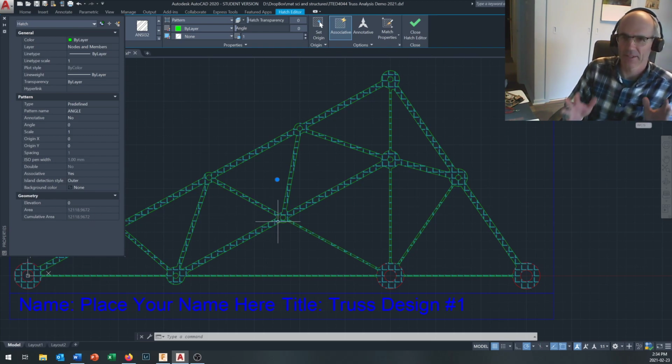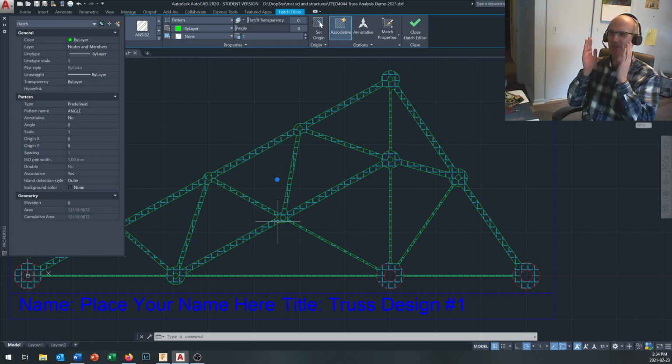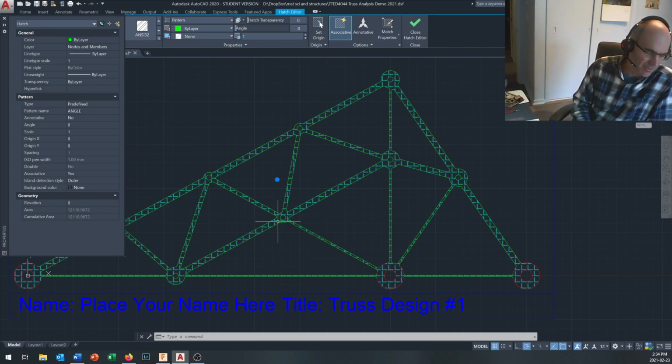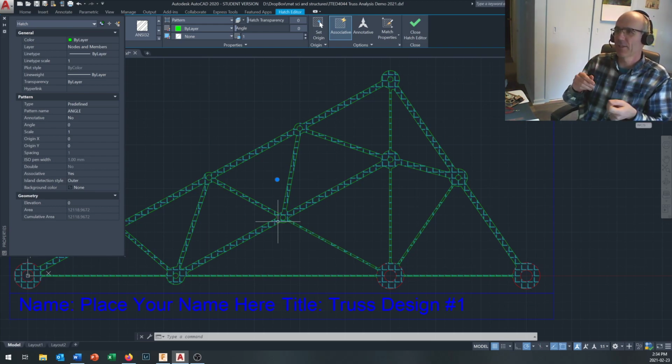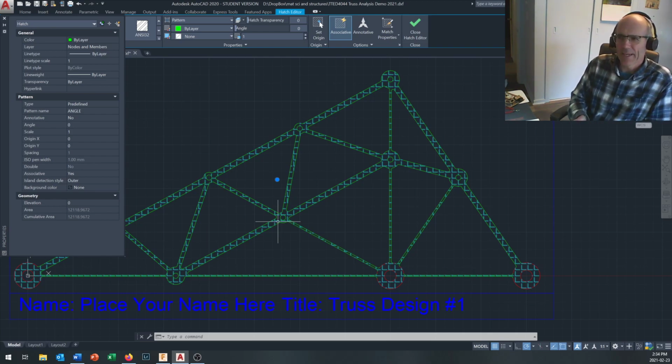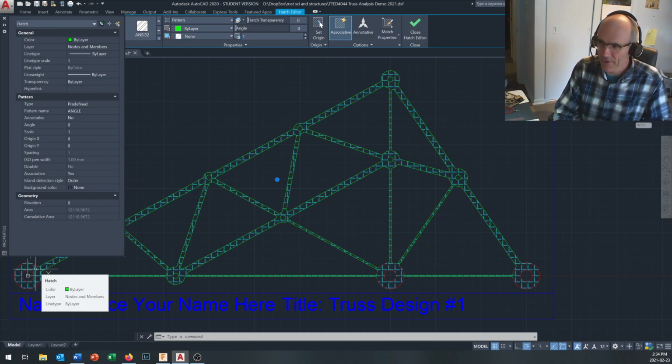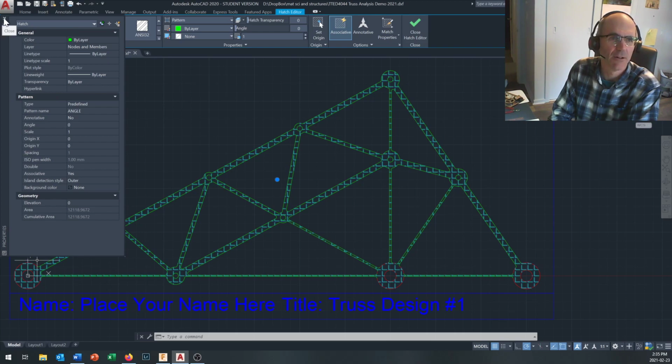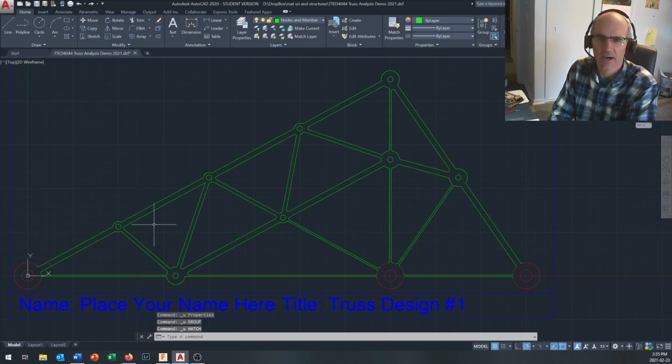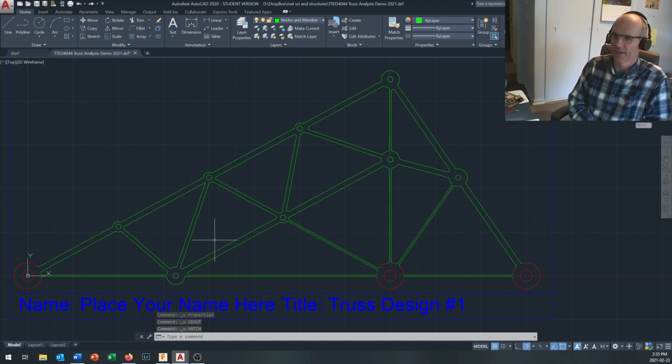this tells me that my truss right here, this piece of MDF, is going to weigh 32.7 grams, which doesn't sound too bad because when I go make it a two-sided truss, that's going to take me up to 64 or 65 grams, and that might leave a bit of mass left over for the wood joiners and the glue that's going to hold it all together. Will that be enough? I don't know just yet. That'll take a little bit of experimentation and calculation, and Fusion 360 will actually help us out a little bit with that. Okay, so once you've got that area and used it for your mass calculation, you can close the hatch properties and undo that. You don't want to keep that hatch on there.